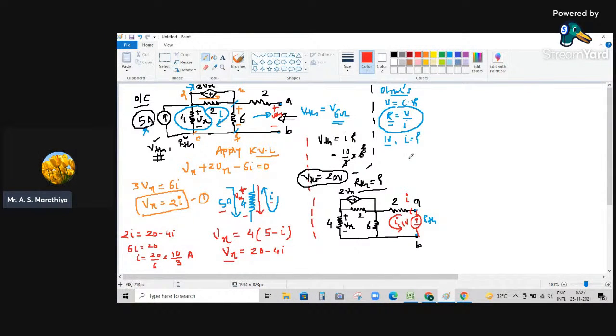This is very important. In the same way, we may have one more current flowing in the circuit, in this particular mesh. Let us consider that this current also flows in the anti-clockwise direction, and call it I1. So here we now have two currents. First is I, which is supplied by this 1 volt voltage source, and then we have one more current, I1, flowing in this mesh in the anti-clockwise direction. Now our objective is to find the value of this I.